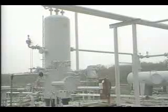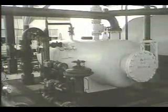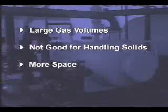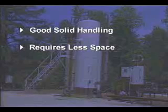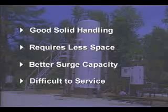Selection of a separator type is based primarily on gas handling requirements and space availability. Horizontal separators are normally more efficient than vertical separators in handling large gas volumes, but not as efficient at handling solids. They also require more space than vertical separators. Vertical separators, on the other hand, have good solids handling capabilities. They require far less space than horizontal separators and have much better liquid surge capacity, but they are also more difficult to service.